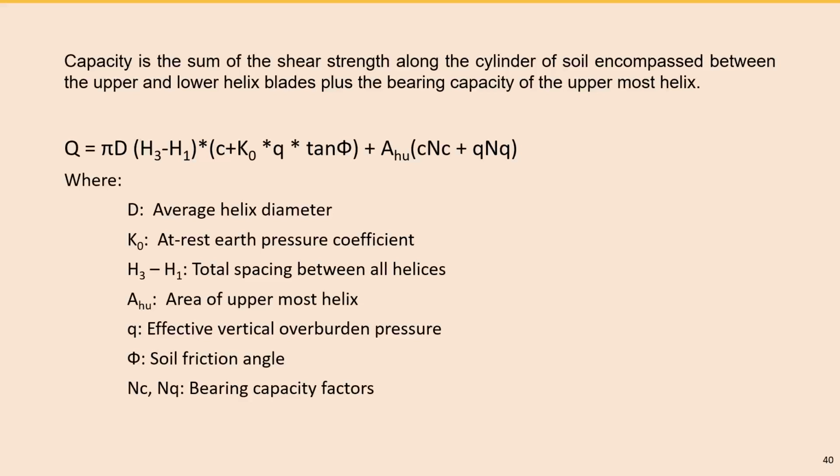You cannot find it the opposite. In the helical pile industry, the lower helix is the smallest, like a tapered pile. Sometimes you can find they use the same helix size, but the largest helix is always the uppermost one.